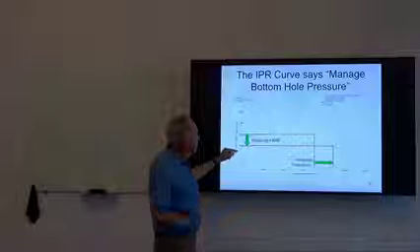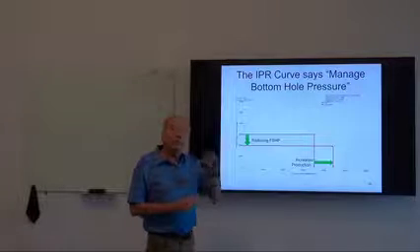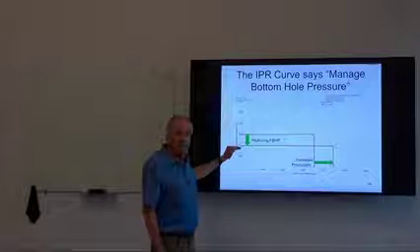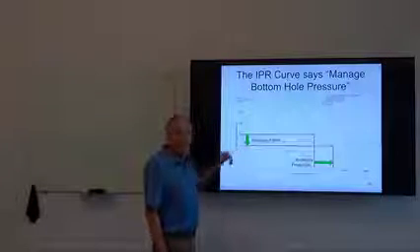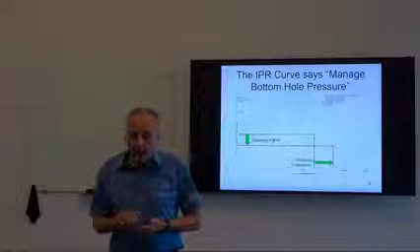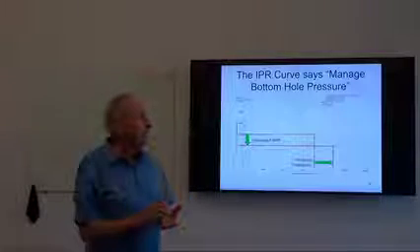Keep in mind that this pressure at the bottom of the well is also important relative to the surface pressure, and that if we take away too much of that drive, then we just may not have sufficient drive to operate the well continuously. It may become very erratic.